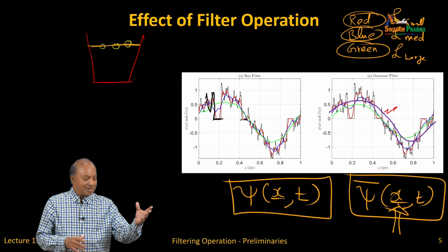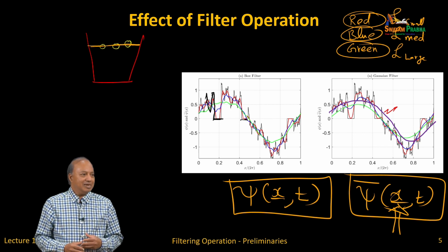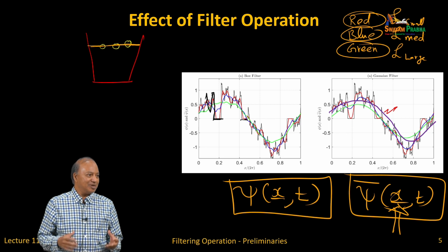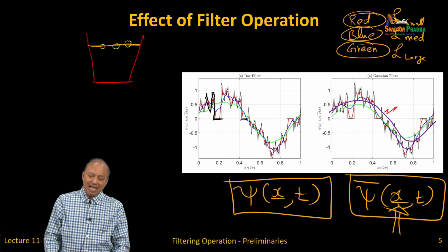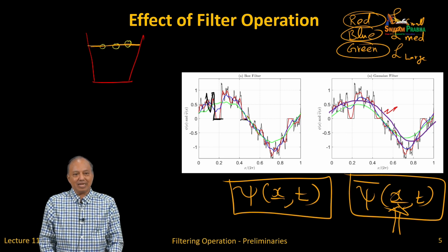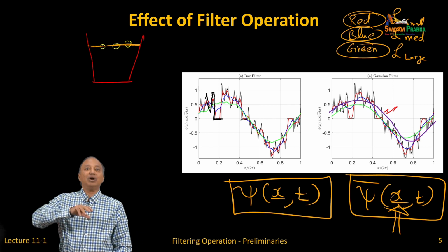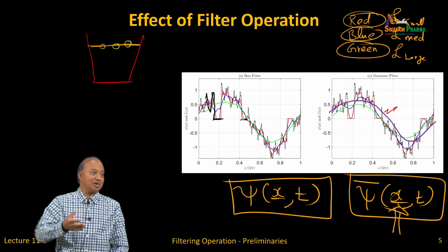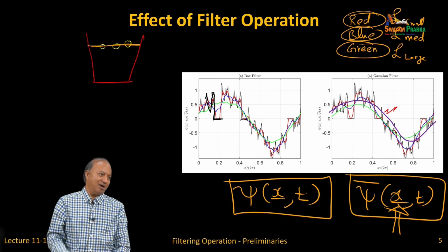So in that sense, you are right that even the classical approach, make your grid half in every direction and you compute, and if your answer is the same, then your grid converged. Here it is not quite that way. Okay. But what I said is difficult because if you do a very fine grid, then you have to apply a coarse filtering on top of it, then you can compare a coarse grid calculation. So it can be done, but it is hard. Okay.